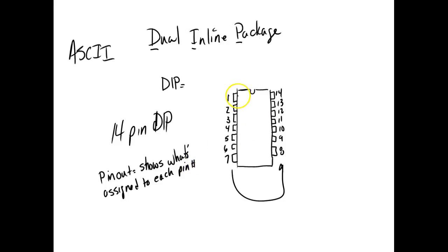So I'm going to come over here and do this, and that would be that whole circle. So I've got 14 pins to work with. An inverter needs 2 pins. So how many can I put in there? We put 6 of them, right? Because people keep forgetting we got to power this thing up. But all these circuits are inside there, so they share the same power pins.